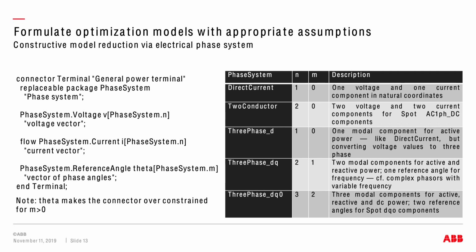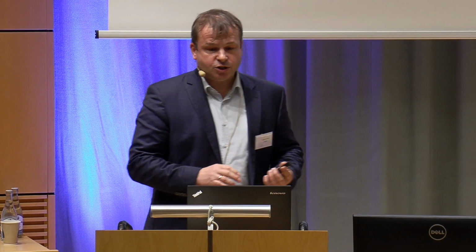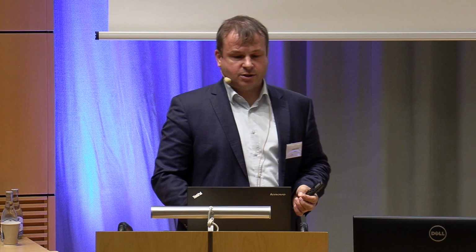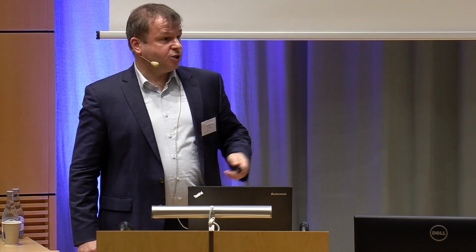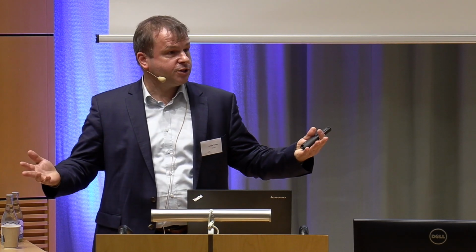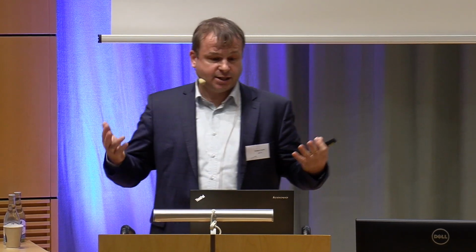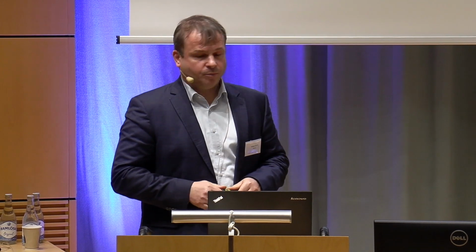And here we borrow, Hans-Jörg did it already, technologies from the multi-body library, that we formulate an over-constrained connector such that in the end of the day, the same phase angle gets communicated to the whole system. And the Modelica tool takes care about over-constrained connectors. It's a problem, of course, if the structure changes. If you break a system, split one electric system in two electric systems, you somehow would need some recompilation of the whole system. So we don't treat this so far.